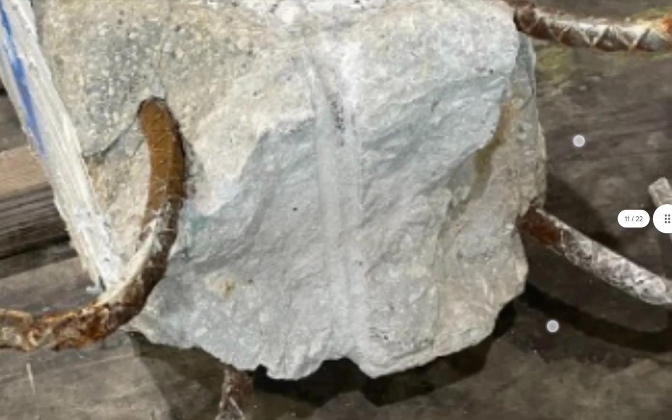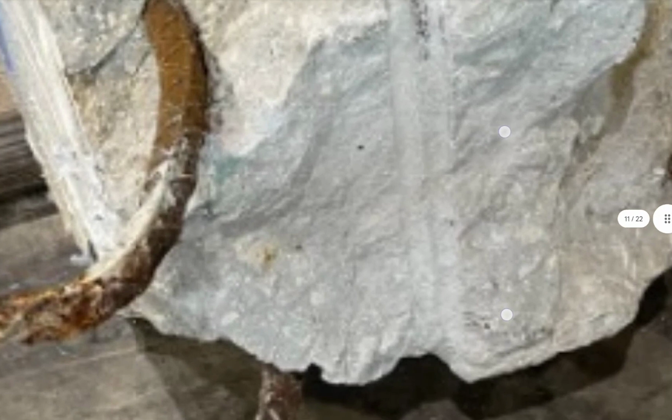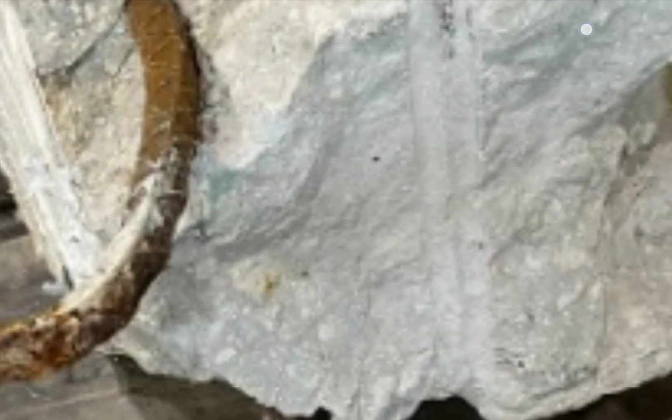I would really need to see a little more. We zoom in. We look at it. I'm trying to find the profile inside these ribs inside here, and it looks like that's the rib. That's where the two of them meet and create that little void, like this. So that's that little, see the hill? See what's left behind? This part. That part is this part in the middle. I'm going to remove it, and you see it there. That would tell me the sizing of the rebar because I have part of it right there. So I'd be able to tell you what size rebar was inside that hole by the measurements there.